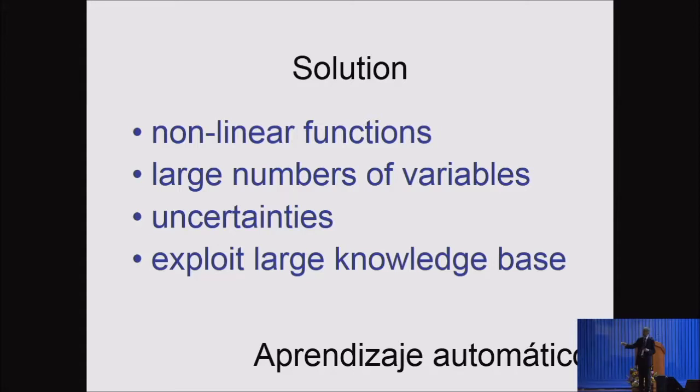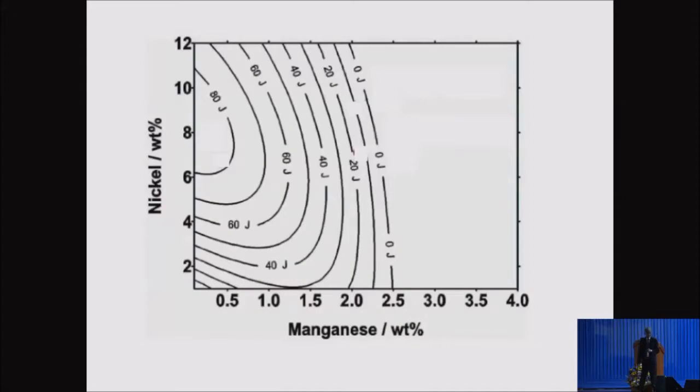So if you make a martensitic welding alloy, it will transform at a low temperature, and it will completely cancel out the thermal contraction strains. But we need to make sure that the toughness is fine. So we designed a number of welding alloys using our mathematical models, and we came up with this, which goes against what we normally think.